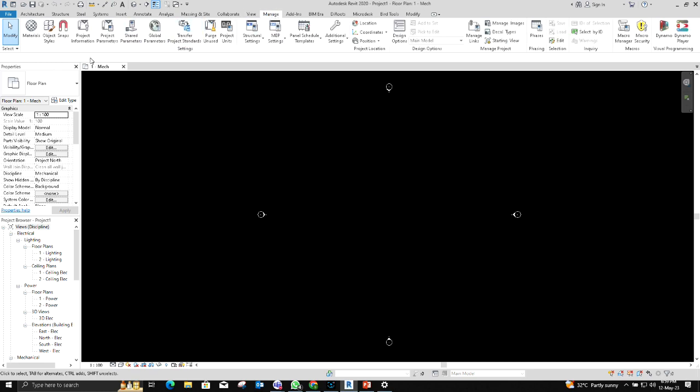So here in the Manage tab, there are parameters. Whenever you start a project, you have one reference file for that. Your senior engineer, like a BIM coordinator or BIM manager, will give you one file. From there you have to transfer all the details, like pipe types, piping systems, ducting systems, duct types.